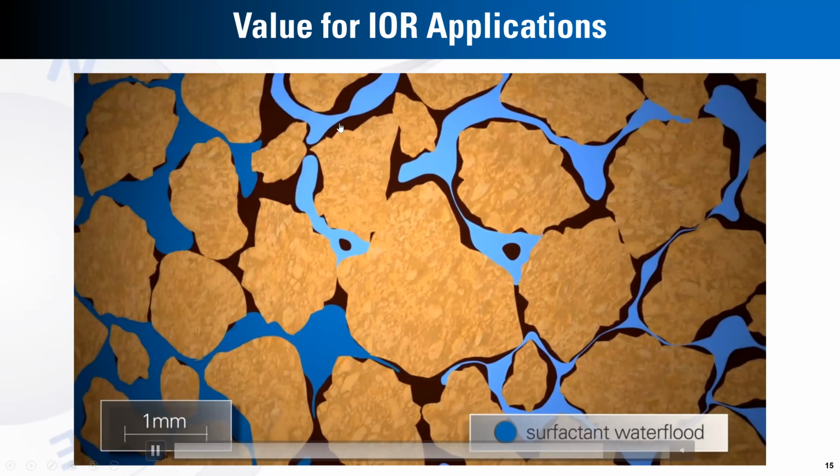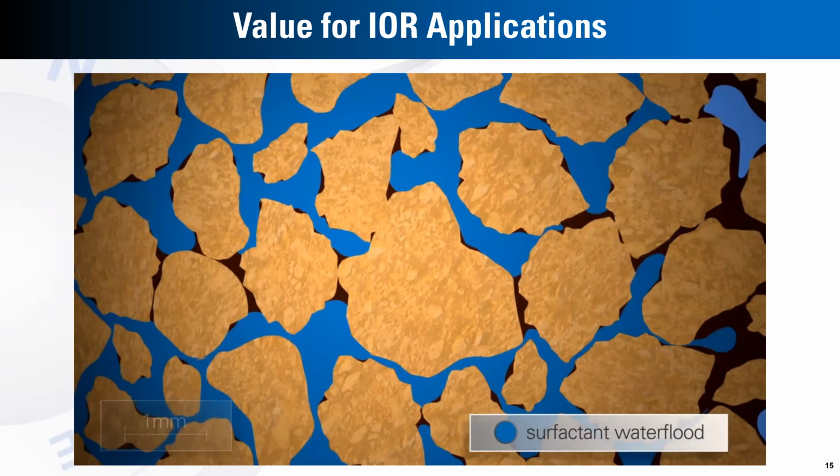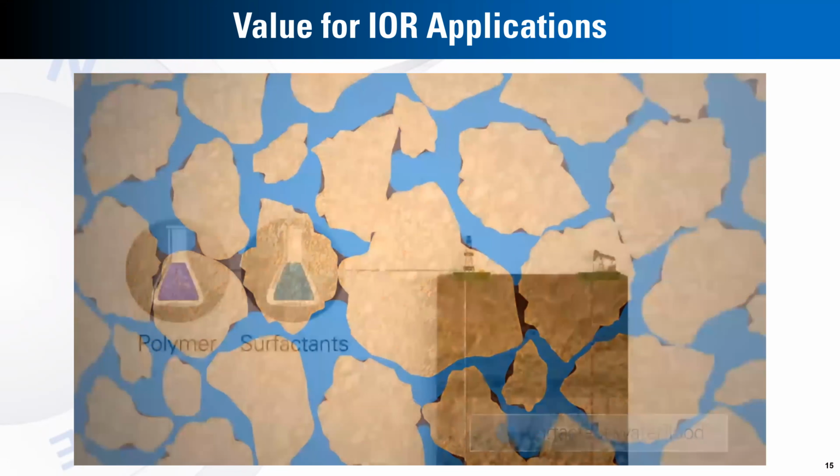This is related to understanding how to minimize the residual oil by understanding the type of wettability of your system and the relative permeability, and how to control the mobility of different fluids to maximize recovery by secondary or even enhanced oil recovery techniques.